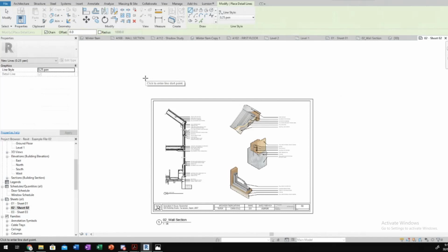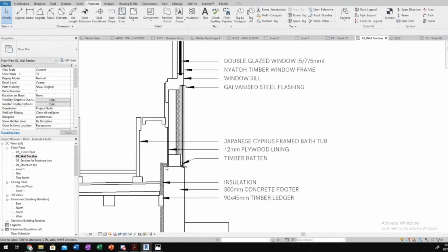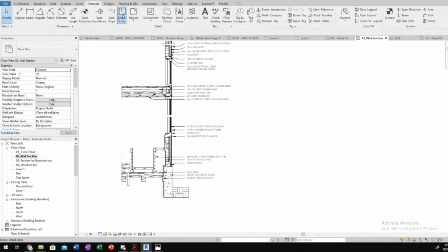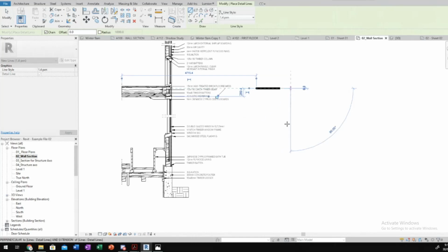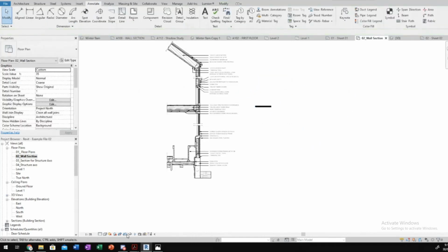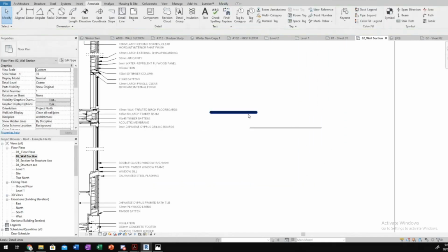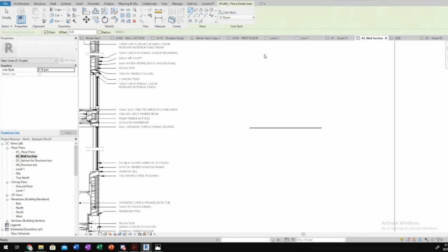And so now I want to show you a few different shortcuts that really, really help out. So we'll just go to this wall plan quickly. So say I have a line here, and you can't see. So let's change that to, there you go, that's nice and thick. Oh, and the reason you can't see that as well, because my crop region was cropping it all out. So let's make that a bit bigger. Yeah, there's that line. On pen 8, there you go.